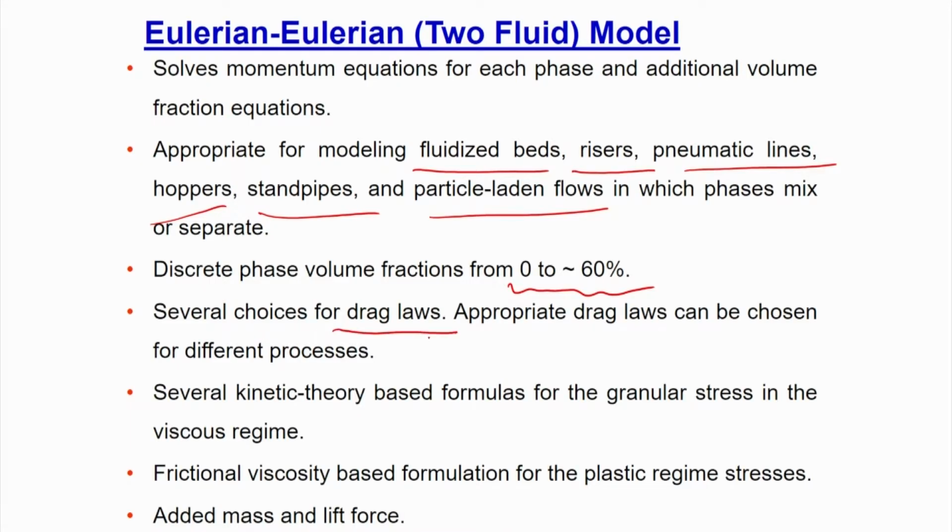If you see, all the ASM restrictions are now removed, and you can use whatever drag you want for your system. You can write your UDF or your own code to use the drag, so it does not restrict your drag model. You can use the kinetic theory of granular flow to solve the granular stress in the viscous regime, and it means what?